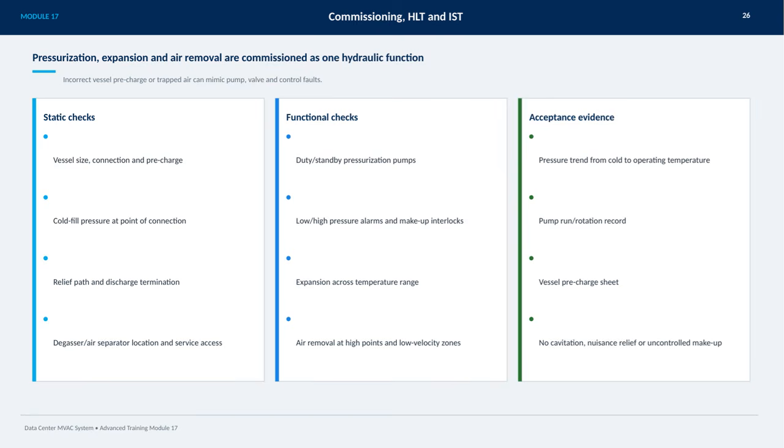For acceptance evidence, we look at pressure trends from cold conditions to operating temperature, review pump run and rotation records, and examine the vessel precharge sheet. All of this confirms that there is no cavitation, nuisance relief, or uncontrolled makeup, ensuring the system operates reliably and efficiently.